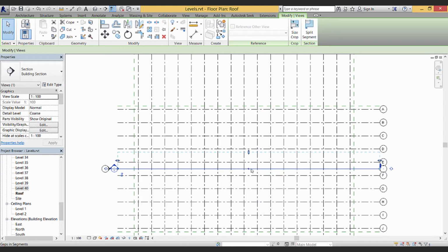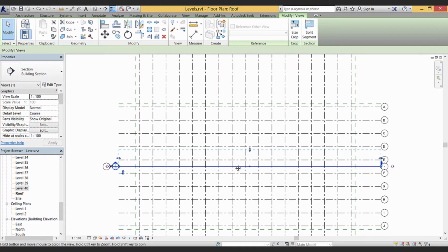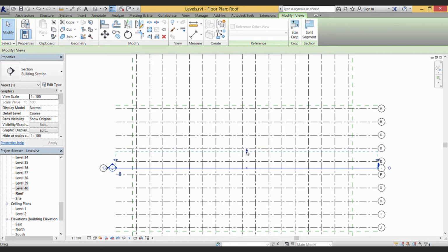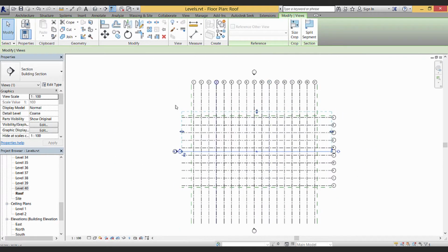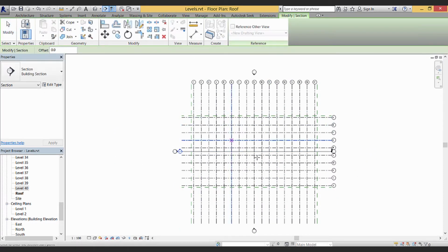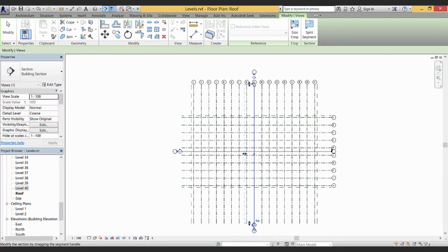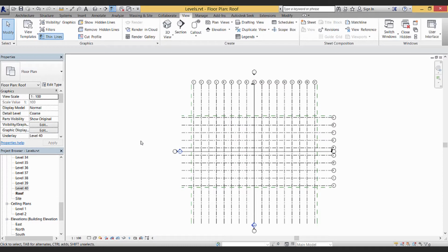Once you've created the section, you will see that it's already selected, and you have this extents control that you can drag. Let's drag this just outside our horizontal grid, so we can see the entire building section that's going to be inside this area here. Repeat this command again, going from south to north, now snapping to the grid elements, grid number 9 actually, like this.